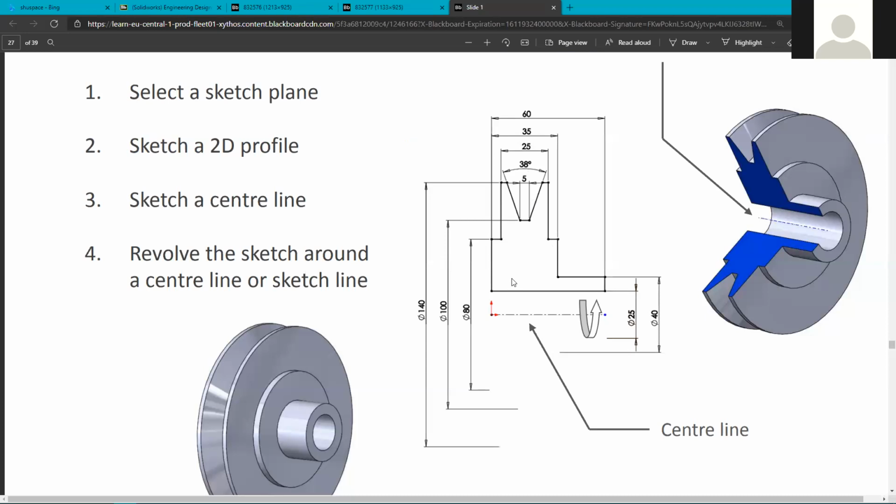So that's one of the problems when you're creating these sketches and you put too much complexity into a single sketch. They become very hard to control, and by extension they become very easy to ruin by making changes to the dimensions later on. So if you came in and said, well, I want to change one of these dimensions, let's say this 35, it seems obvious, but if I was to reduce that down below 25, these little shelves here, so this feature, would end up inverted and it would cut into the part.